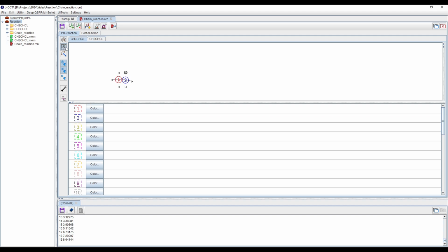Next is to assign the symmetry points, and these symmetry points tell the system that these are symmetrical points in the monomers, to save some computation power. So for that case, we can use these symmetrical points. Since, as you can see, for this one particular carbon atom, these hydrogen atoms are symmetrical, I am going to name it 111. So if my system has to calculate for this one hydrogen atom, it will give all the values similar to these other hydrogens.